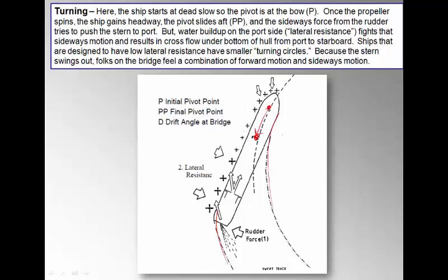As I'm pushing my rudder over to the side, I'm creating a high pressure area over here because I'm basically piling all the water up on top of itself. At the same time, I'm creating low pressure over here. Not a pure vacuum, just low pressure. And I'm doing the same thing up on the bow, only in the opposite direction. As this is pivoting through, I'm creating low pressure up here and high pressure over here.